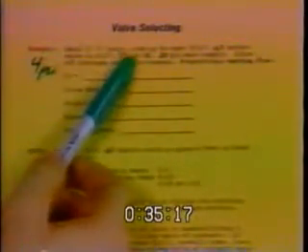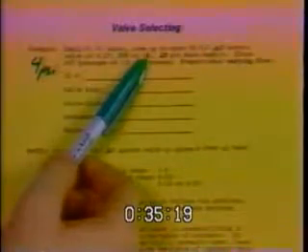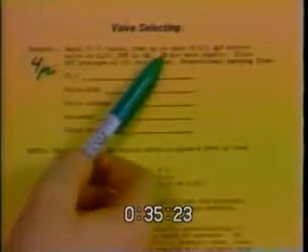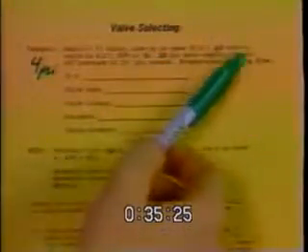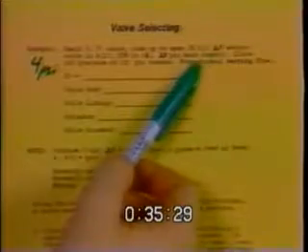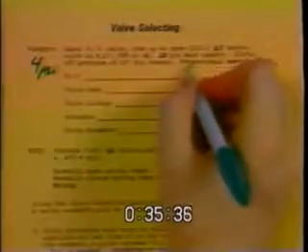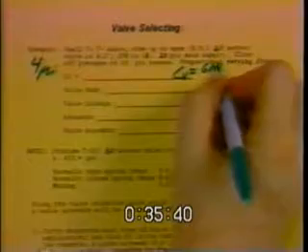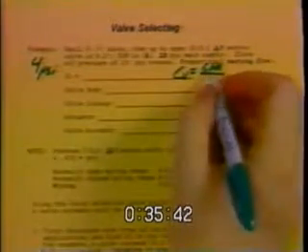Now the gallons per minute is going to be 16, and we have 20 psi main supply. That's talking about a pneumatic system, 20 psi main, and we need a close-off pressure of 10 psi. And I'm going to be proportional, varying the flow. The first thing I want to do is calculate my CV. Again, CV equals your gallons per minute divided by the square root of the pressure drop.